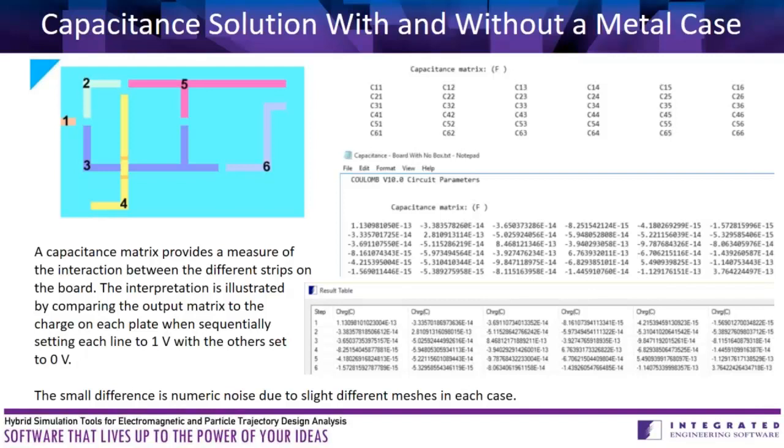But we have solved this in a grounded simulation, meaning that somewhere out there, there is a real world ground that will in general hold a little bit of the charge. That's what makes the voltage decay to zero as you move far away. And because of that, the matrix will not be quite symmetric. The two solutions did mesh the model a little bit differently, so if you look at enough decimal places, you will see some small differences.